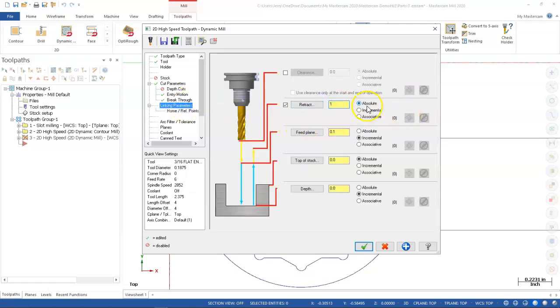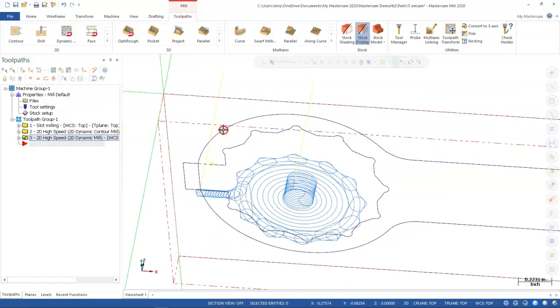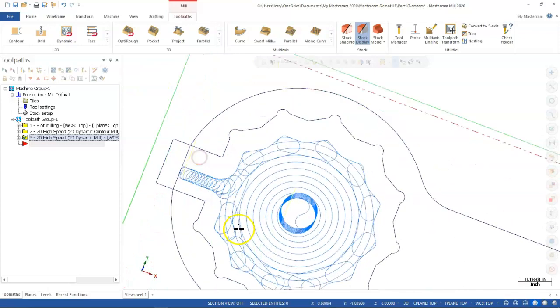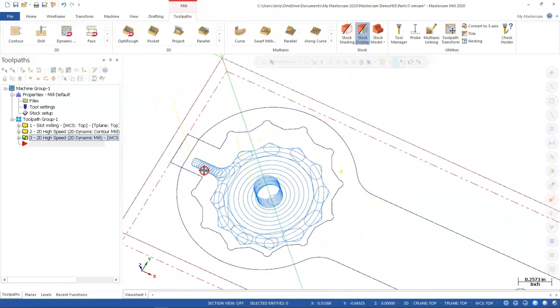parameters, stay with 1, keep our absolutes for now, and then the minus 135. All right, so regenerate, nope. All right, so the step over mounts, helical in, make sure it cleans up the center. And then the whole thing with the dynamic clearance is that it takes those little nibbles rather than in a pocket plunging straight in. All right, so it's going to be a little gentler on the tool.